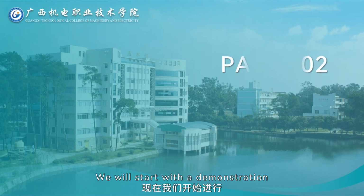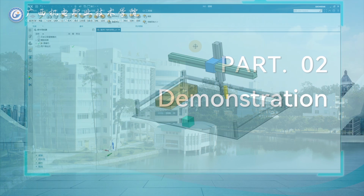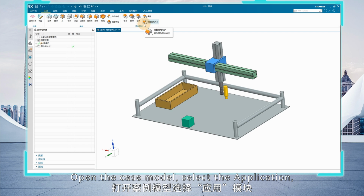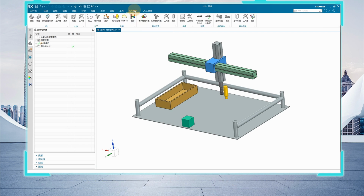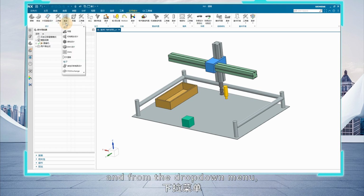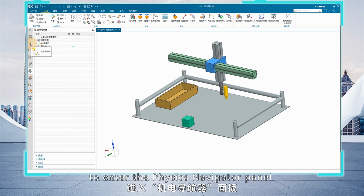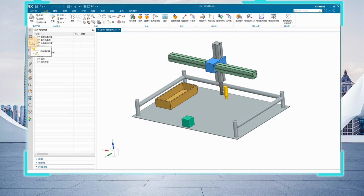We will start with a demonstration of the specific operation steps. Open the case model, select the application, find the panel of design, choose More, and from the drop-down menu, select Mechatronic Concept Design to enter the MCD module. Select the Physics Navigator from the left resource bar to enter the Physics Navigator panel.